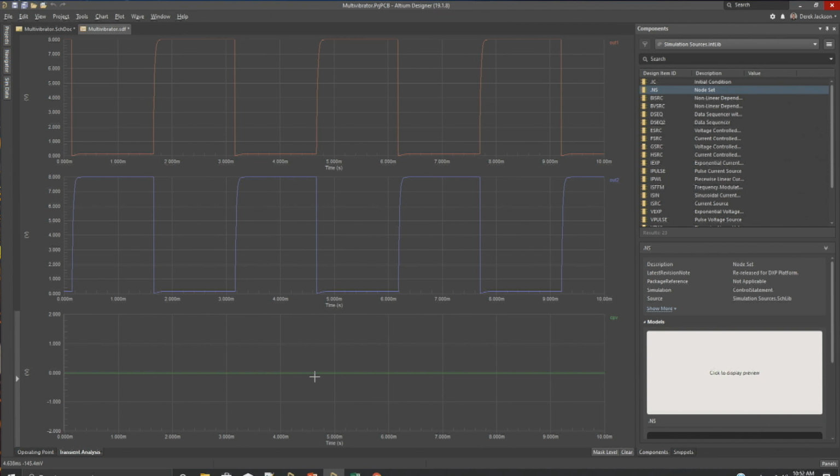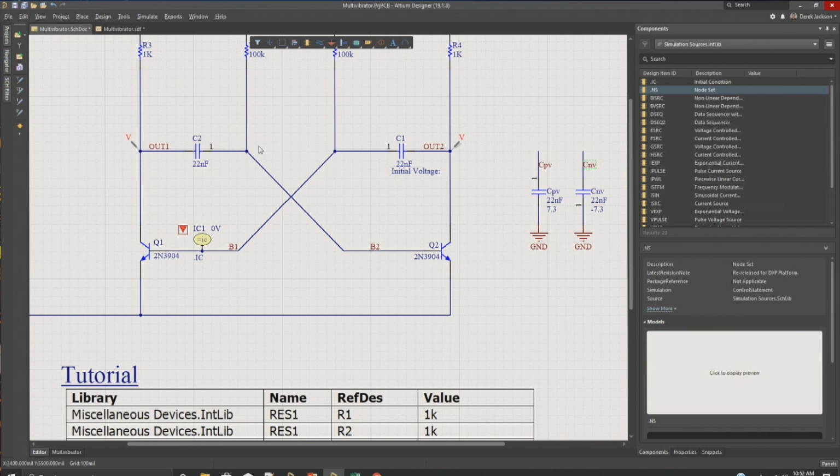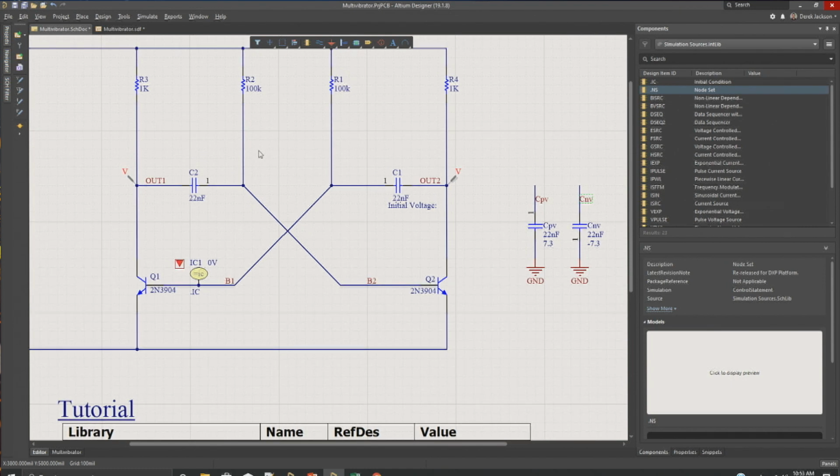When Spice first does the initial steady state, it opens all capacitors and shorts all inductors. That's how it calculates the steady state response. So we see that's 0. There was enough variation in the circuit to get these to start oscillating, but sometimes there's not, so sometimes you have to set a value over here. I was experimenting with putting an initial voltage on here. I don't have anything set there for now.